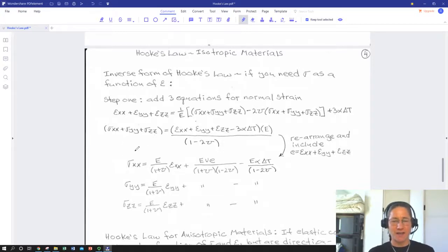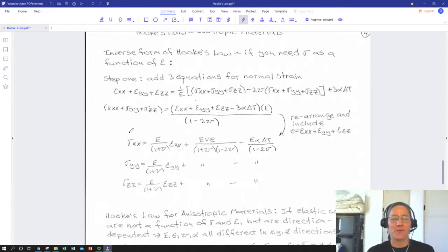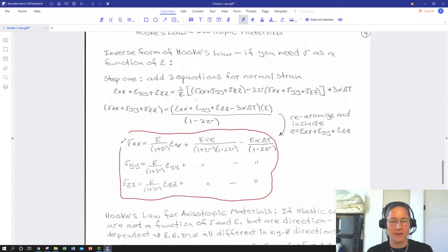in terms of strain. Again, I won't step through the algebra, but I have written some of these out, and you can basically substitute in for them. They're a little bit long, but in this case, we have stress on one side and strain, modulus, Poisson's ratio, and then this last term will only be present if we have a temperature change. Remembering alpha is almost always given in Kelvin, so it'll be in some kind of number per degree Kelvin typically. Check and see which temperature unit it's expressed in.